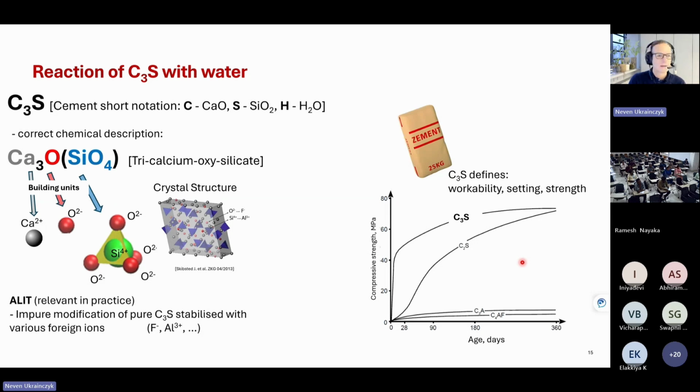He got his PhD, and now he's working on this CeraLite, which is pure calcium silicate. Then we don't have aluminates, which is also good from the durability point of view, because you don't have delayed ettringite formation. From the durability point of view, it would be much better to have only silicates. But why are there aluminates? You know why?